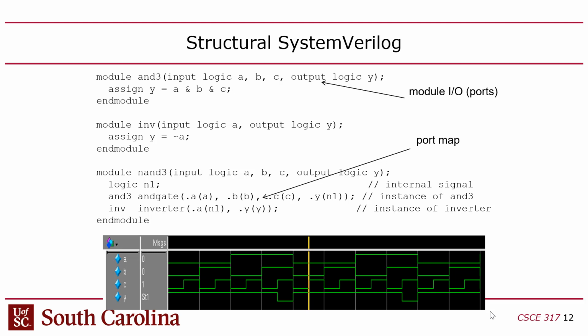Okay, so then we use ModelSim to debug this stuff. Waveform editor, discrete event simulator. But here's the problem though. In this class, you really can't use that. Not if you want to test the interaction between the Nios processor and your hardware, because we don't have a way to simulate the Nios processor.